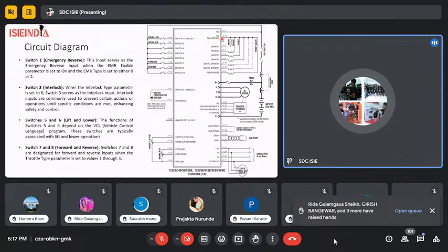The second pin is going to be connected with the contactor, to create a magnetic field in the contactor to move from NO to NC. So this is going to be connected with contactor 13 and pin number 6, and these are like driver 2, driver 3, driver 4. These are the wires for the EM brake, pump, like I told, the forklift and the hydraulic pumps. These are also used for specific functions to control them, to run them.